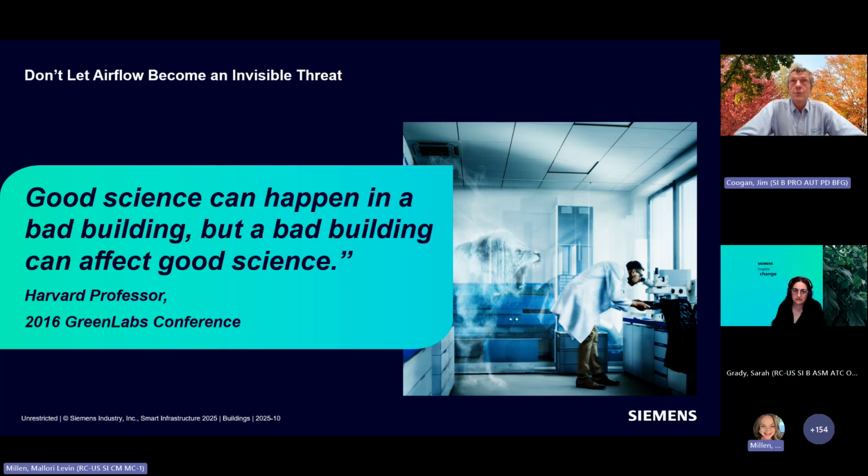Great, thank you. I think I'll just throw in one more point. A big part of what it takes to make a particular renovation feasible is what are the airflow ranges of the equipment that's installed, and that means the mechanical equipment. What are the min and max ranges that it can work reliably at, and the control equipment, especially the sensors.